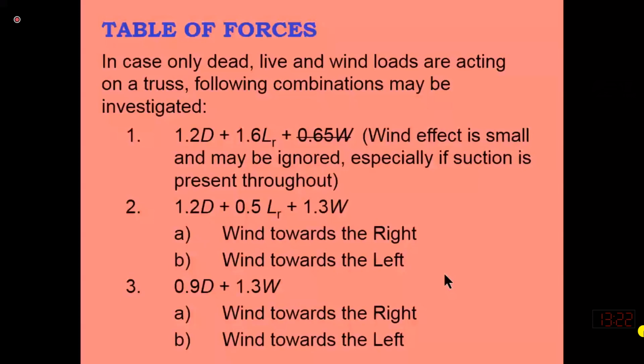If we know the analysis of the truss due to this component and due to this component, and we add them up, the amount will be the same. So actually, by the principle of superposition, the effect of the resultant force on a structure will be equal to the effect produced by the components of the force. In other words, let me write the condition over here.